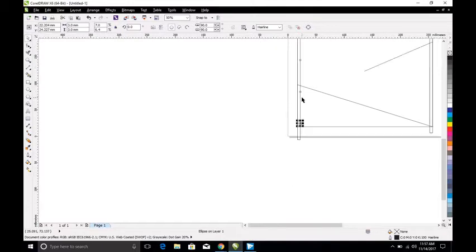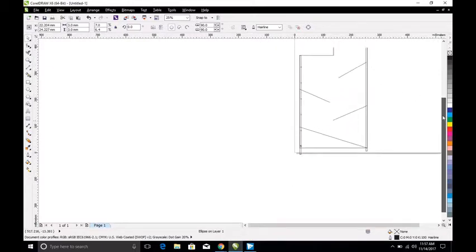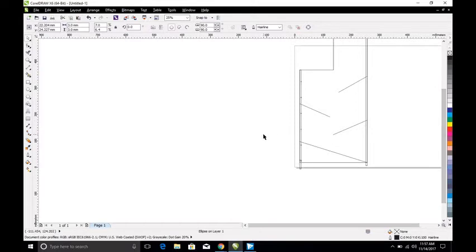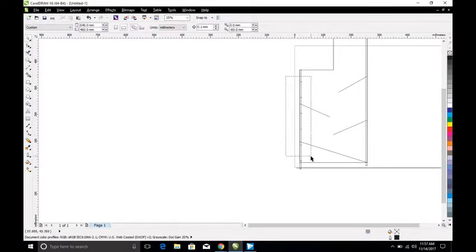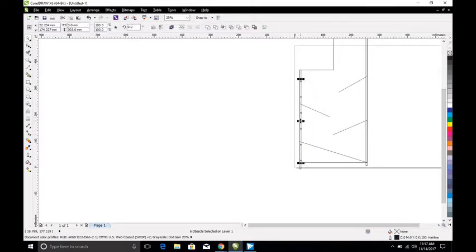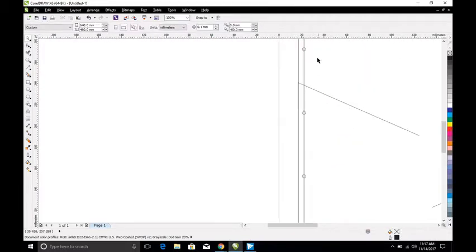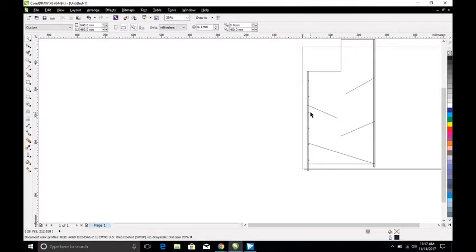What I'm going to do now, am I happy with that? I'm actually going to take those and move them up a little bit. See, if I go like that, I can move it all over the place. If I hold my Shift button down, I can just move it straight up, and it'll move them on the line. So holding the Shift button allows you to move something in the X or the Y direction, so 90 degrees left or 90 degrees up and down, yeah?